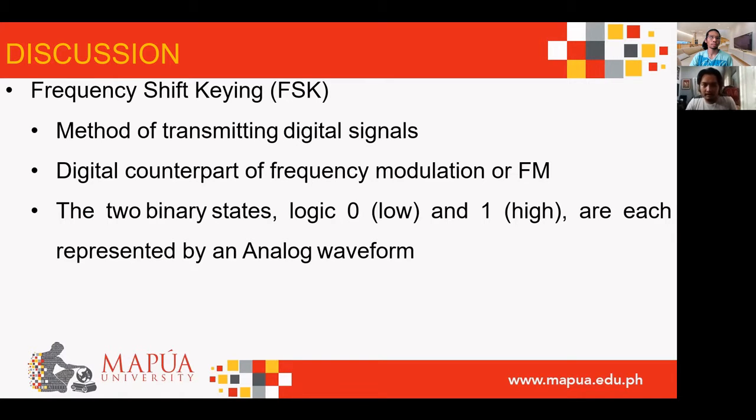It is also defined as changing or improving the frequency characteristics of an input binary signal according to the carrier signal. Amplitude variation is one of the major drawbacks in ASK. Due to this, the ASK modulation technique is used in only a few applications, and its spectrum power efficiency is also low, which leads to wastage of power. So to overcome these drawbacks, frequency shift keying is preferred.